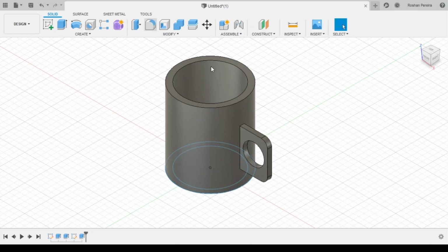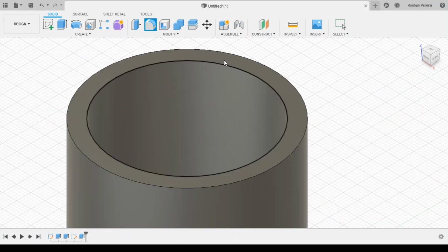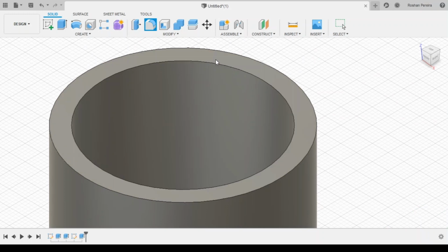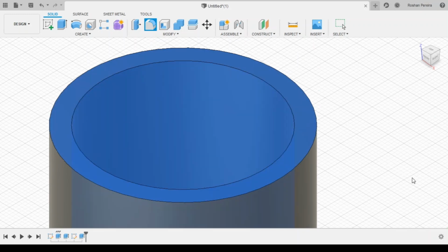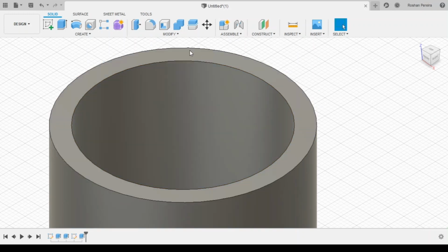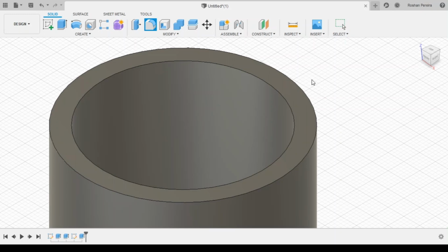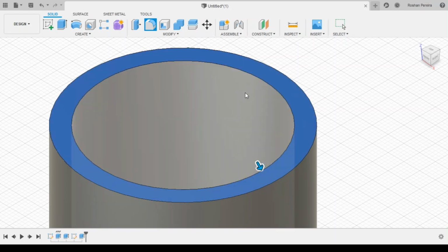You click on it, and then just like before how you selected the two sides, here you select two edges or faces or features. So I'll zoom in by scrolling up, then I'll select the top part and the interior part, and I'll just say OK. I'll do it again. Select fillet, select the top part and select the interior part.